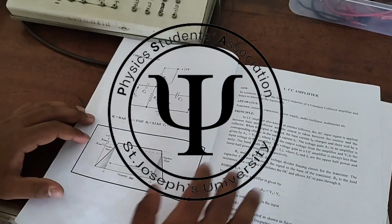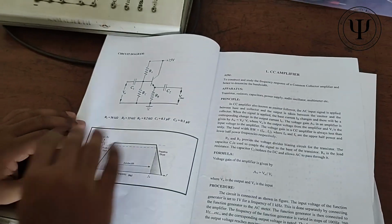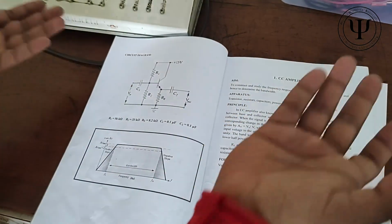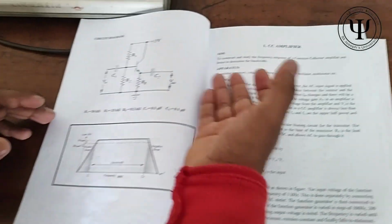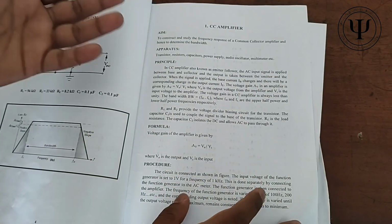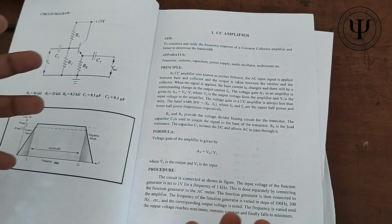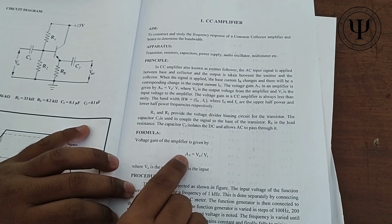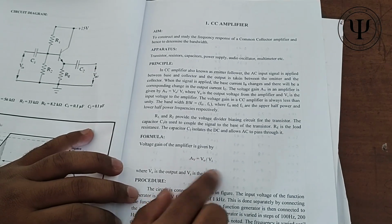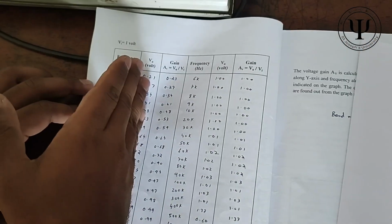Okay, so in this video we'll see how to do the CC amplifier experiment. As soon as you get the question, you have to do three things. First, you have to write the aim. The aim will already be given. So you need to know the formulas. You need to know this formula, that is amplification is equal to V output by V input, right? And then you have to draw this table, basically frequency, voltage output and gain.